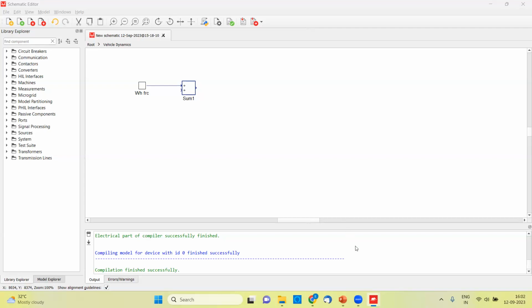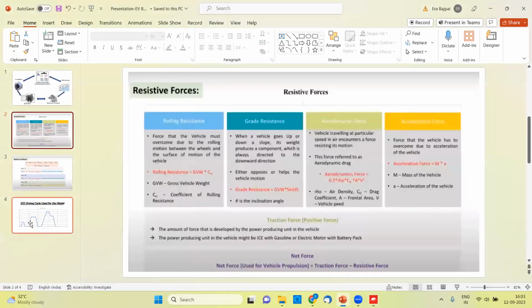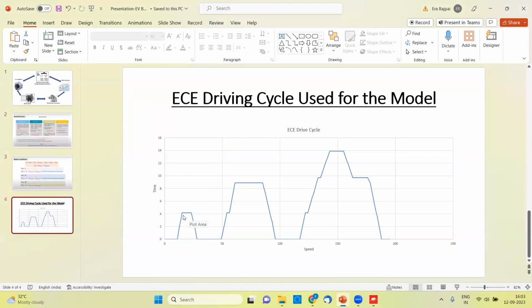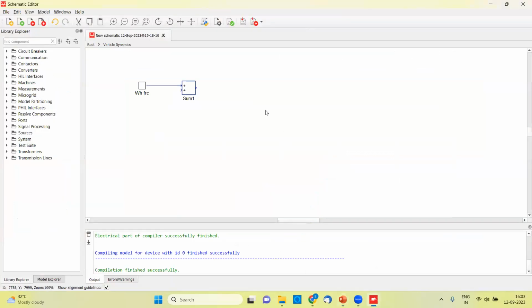So you mean retaining the constant speed? Yes. I understand that in this drive cycle you will be using full acceleration or full brake. But if we try to mimic the real-life scenario, when we accelerate and then lift the throttle pedal, how can we simulate that here? In this model, we have not done the modeling for that particular thing, but if you use the throttle value, then of course, mathematically, you can do the calculation and provide some particular blocks for how you want to change it. You just need to provide some if-else scenario only.